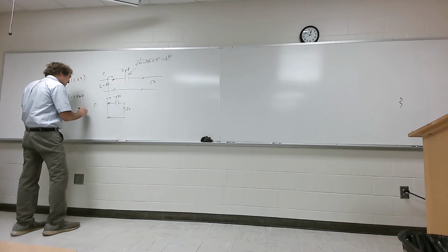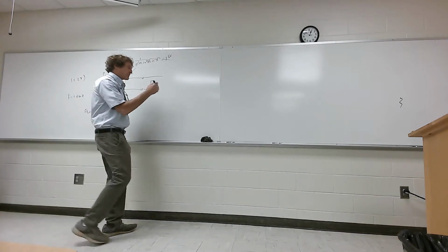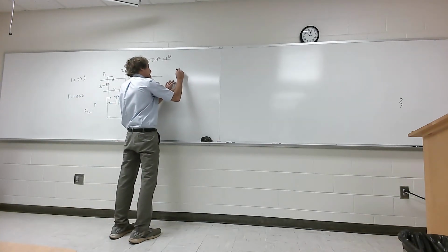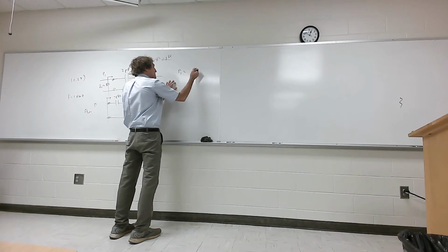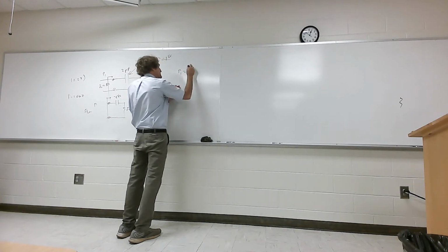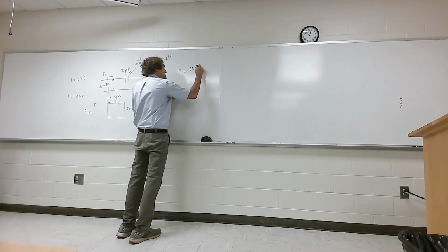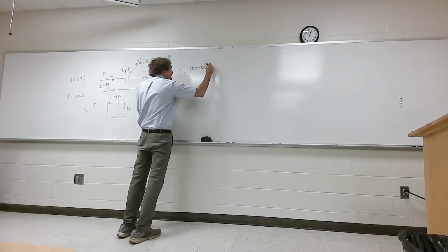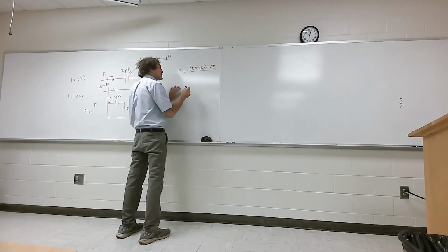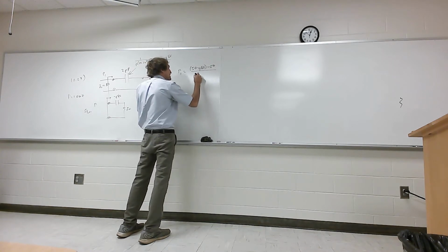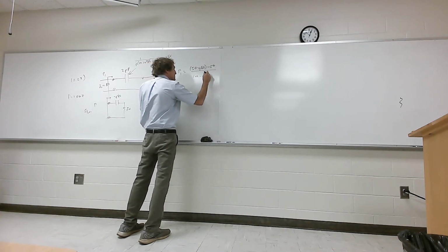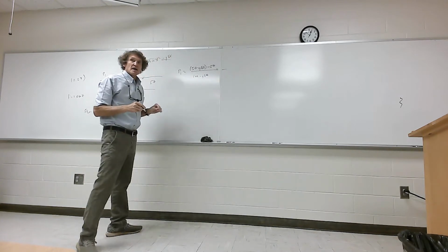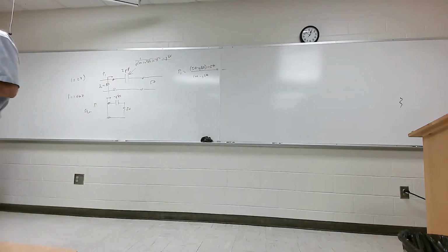I came from a 50 ohm transmission line. So what is that? Well, that's going to be the impedance I'm going into, right? Which is 50 minus j80, minus the impedance I came from, 50, over the sum of the two of them, over really 100 minus j80. So can you tell me what that is? I'm asking you to just do the problem so you'll know how to do something like this if it appears again on a quiz.